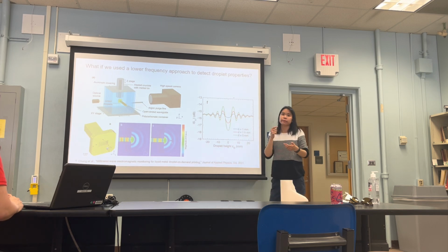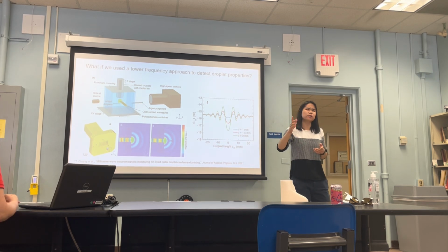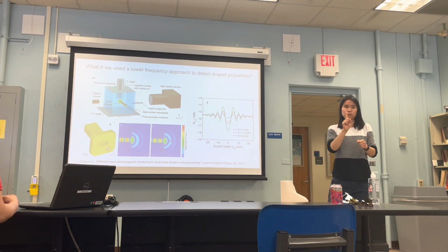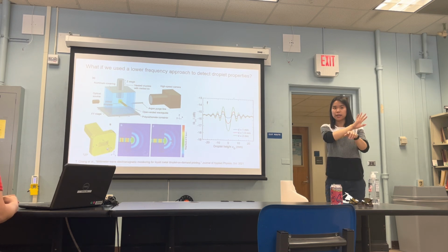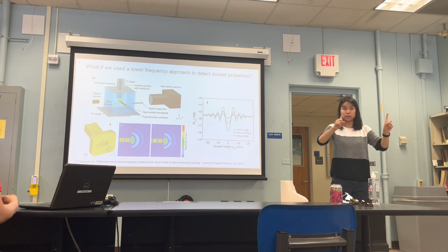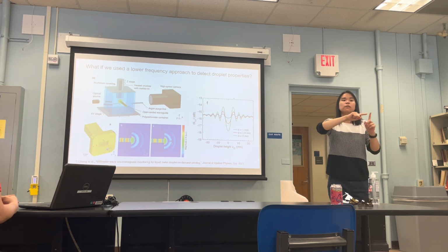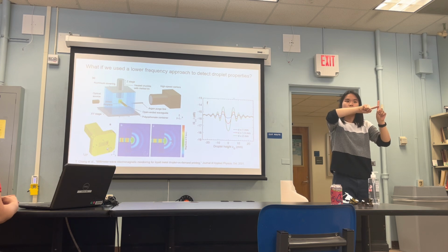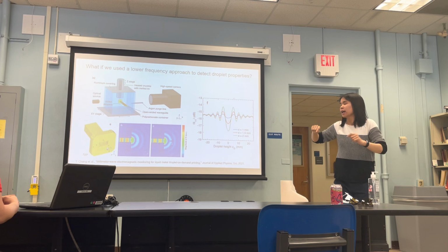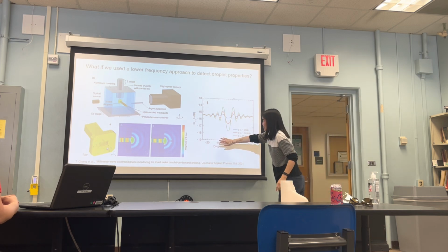And then I sent just a single frequency. I think it was like 50 gigahertz. Just that one frequency. So not like your typical VNA where you're doing a frequency sweep. I just did it in CW mode, and then looked at how that one S11 parameter at 50 gigahertz changed with time. And I also simulated it at some point.